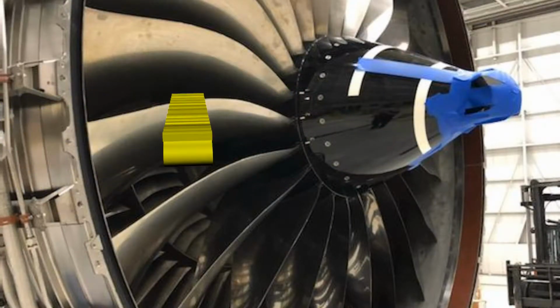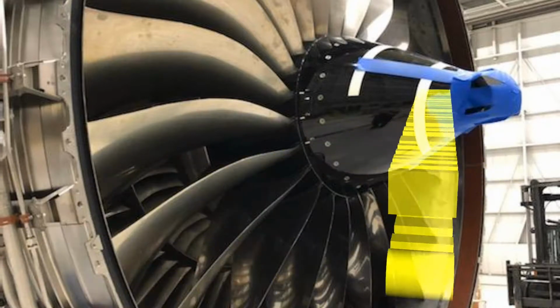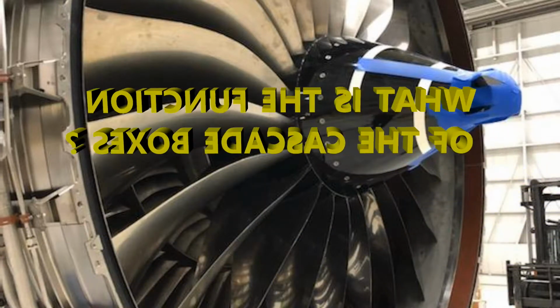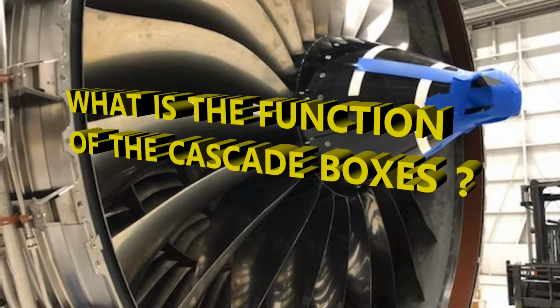Basically here you have a protective cover. This is a cascade box that's installed between the aft cascade ring and the torque box. And what is the purpose of the cascade box? What is its function? Well, it's going to be diverting fan airflow in different directions when you have a deployment of that translating sleeve.